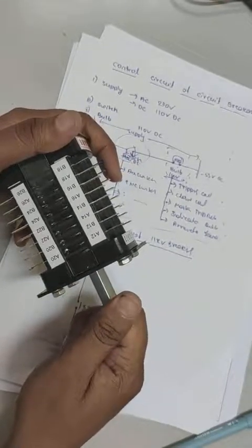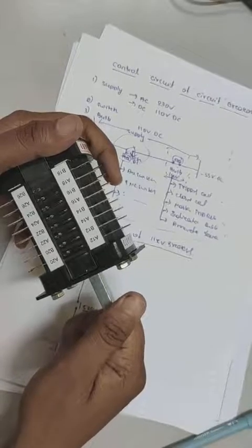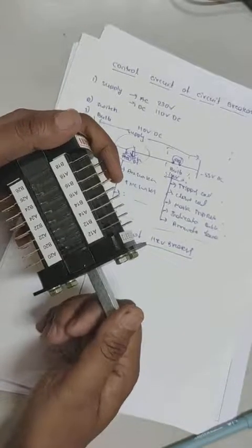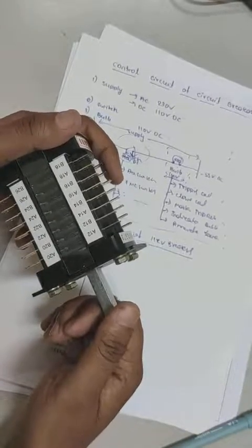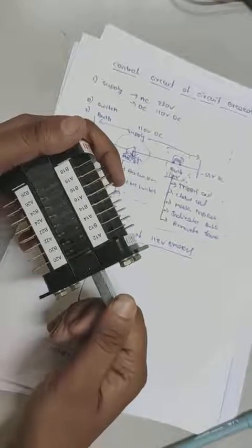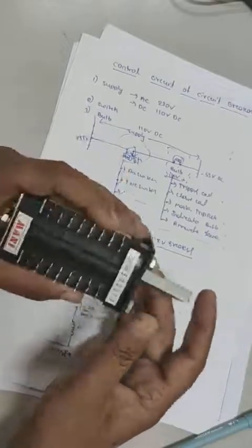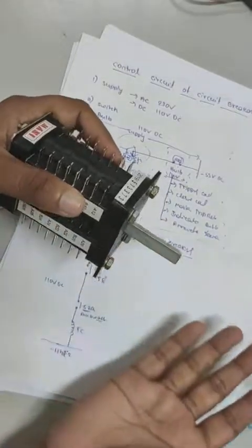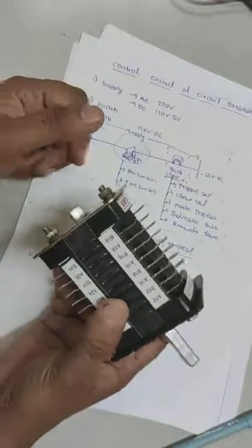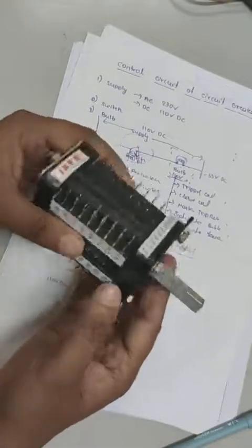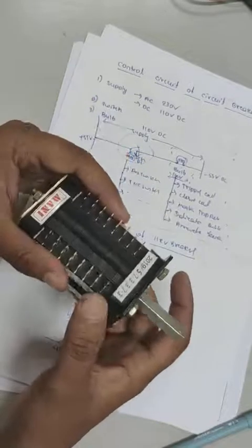For example, in electrical circuits, we give red indication for breaker ON condition and green indication for OFF condition. For that, we need to know the status from the mechanical circuit. So this is the bridge between the electrical and mechanical circuit.